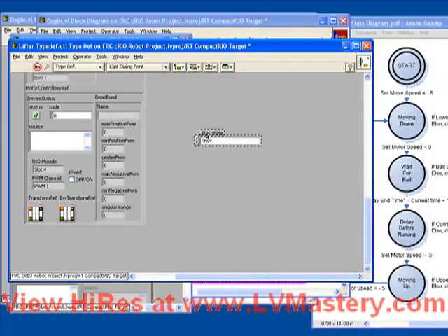And an interesting point here is actually to take that enum and turn it into a typedef itself. The reason for that is you're going to find it makes life a lot easier later on when it comes time to actually program the state machine. So it's just a rule of thumb. Whenever you create an enum, go ahead and create a typedef of it.